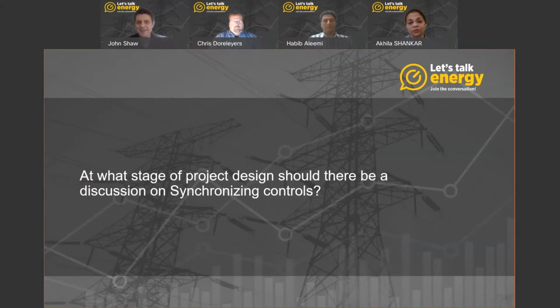That makes sense in a perfect world, but that doesn't necessarily always happen. Habib, maybe can you speak to some of the challenges that arise when we don't have those discussions at this stage? Sure, John. As we mentioned, it's very important to discuss the controls while creating the single line with an expert. These discussions will minimize the cost and complexity of the system. Challenges that we see in some of our projects are complexity of the system, having extra equipment such as breakers, protection relays, and unnecessarily redundant controls and equipment.